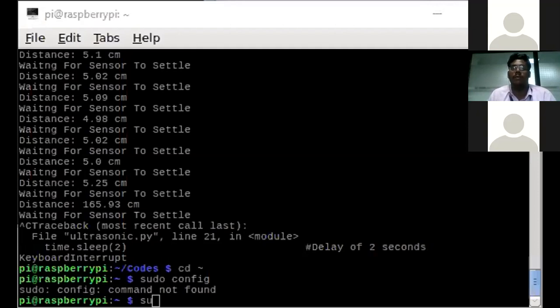Whenever you give 1 as a value to an analog, it takes 0.019 volt. If you give 256, it converts it and acts as 5 volt. So whatever number you give, it acts as an analog. This is how it works.